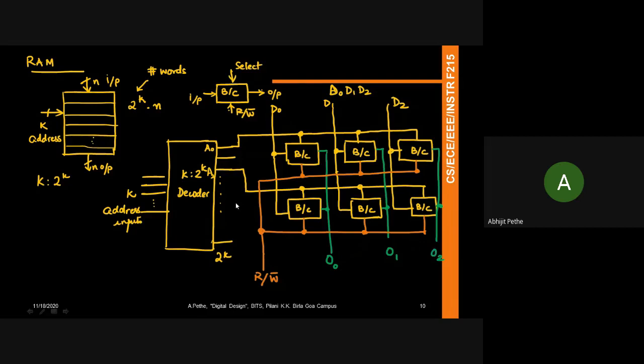Normally, if you're a safe designer, any write operation should be followed by a read operation, right? And why is that? You just want to confirm whatever you have written. Suppose you're writing 100 into a word. You want to confirm that 100 has been written. So a safe design practice is to read it back again, confirm that whatever is written is what you wanted, and move on.